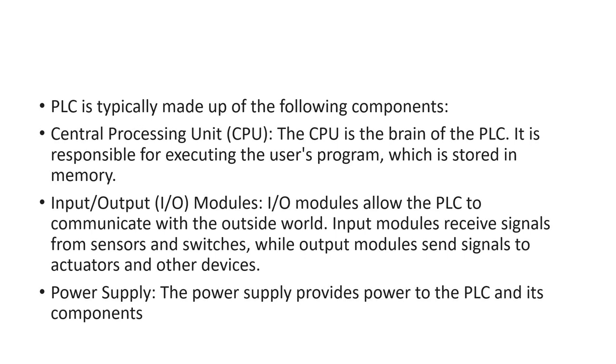Input modules receive signals from sensors and switches, while output modules send signals to the actuator and other devices. I already told that input is from a sensor or it may be a switch, and outputs are signals sent to the actuator or other devices, that is our solenoid valve.